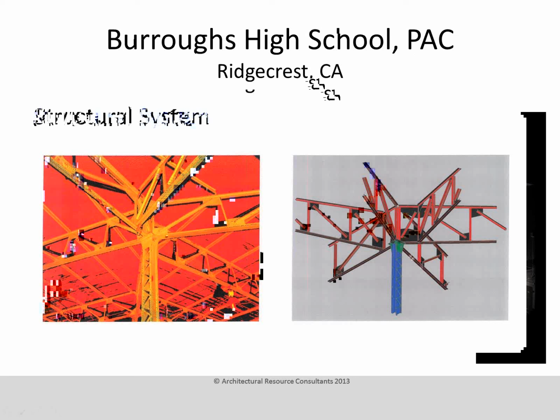This project was a new ground-up building, and this model was created from record drawings so that the contractor could understand where clashes were going to take place in the design. Once the contractor started building the project, they had us go out and scan this, and they were using the scan data again as a comparison check against the model to see where things were being installed in reality versus what was modeled.